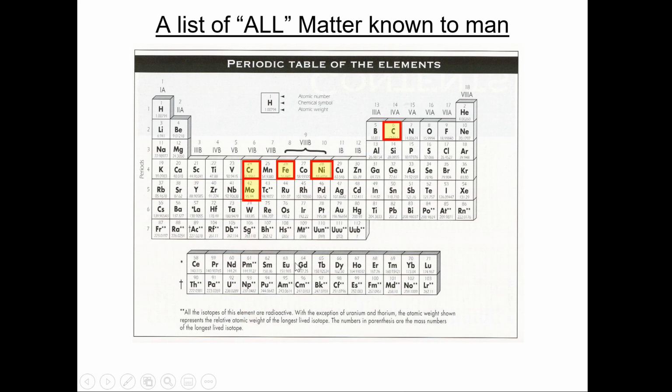Then of course we've got our carbon and our molybdenum. Now we're getting into the elements that give the steel its hardness and its toughness. Vanadium is one of the toughest. When you're digging into vanadium, you're talking about materials that are probably going to be in the Rockwell 60 range. Now these are pretty tough tool steels. Vanadium enriched stuff is usually up in the D2 stuff.